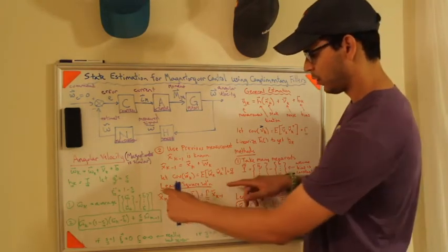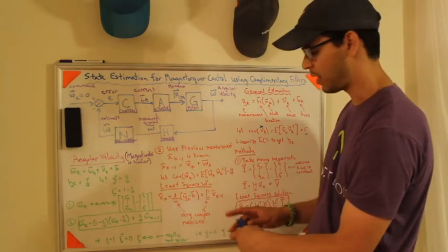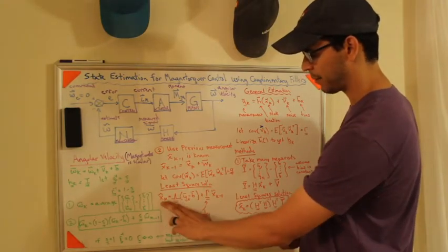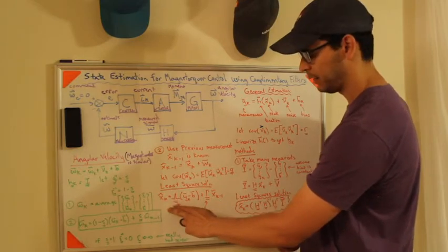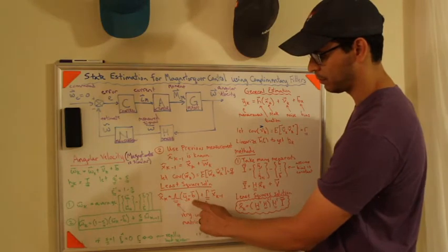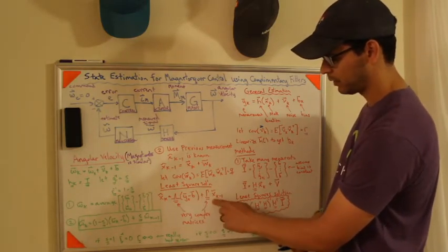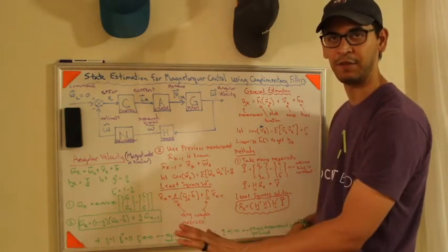Okay, so we're going to use least squares on this. The math for this is very complex, so I'm going to leave that out. But basically what ends up happening is that the next estimate is equal to this lambda matrix times your current measurement minus the bias, plus your last estimate times this gamma matrix here. And again, these are very complex matrices, so I just left them off.